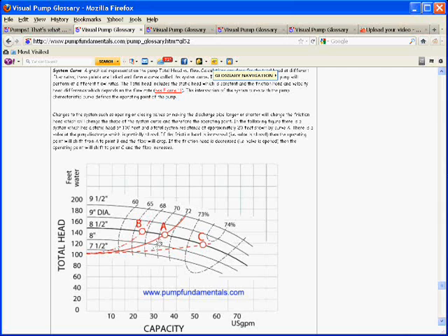How do I generate all these other points? Well, I just do all those calculations again at a different flow rate, and I'll be able to trace this curve right here. Now, let's say that what I've traced now is a pump that's operating, and it's got, let's say, a discharge valve that's partially closed, and this is all incorporated in the values that I've either measured or calculated to get to this point.